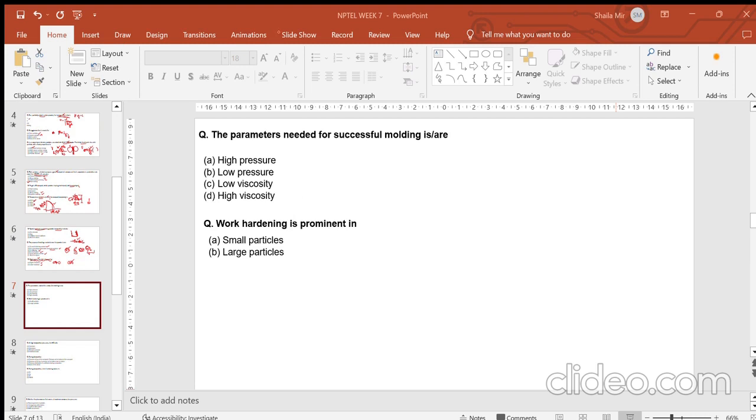Also, you have to remember that when you are mixing powders, the density of the material changes. For 100% copper it is 8.9, but because you are adding some other material with a lower density, the overall density will decrease. It is always a mixture of the proportion in which they are mixed. Because it was mixed only 2%, there was a slight decrease in density, but if it had been added in a larger proportion, the density would be largely decreased. So you will be compromising on the density.